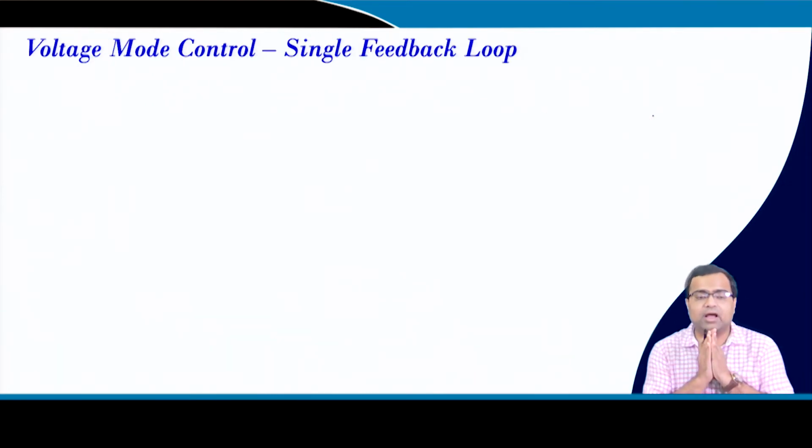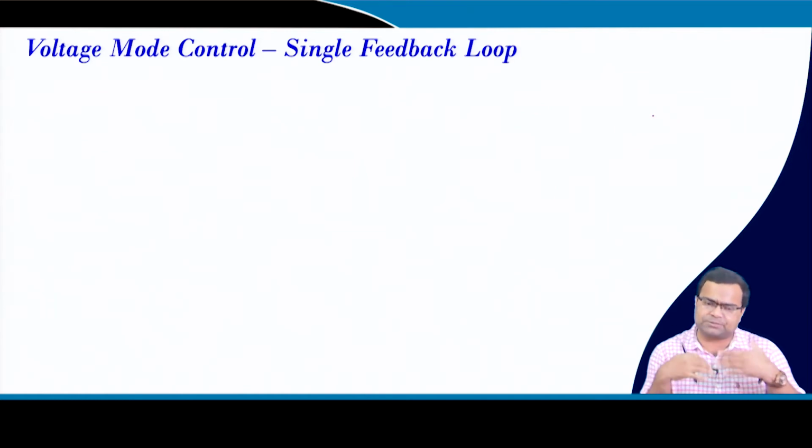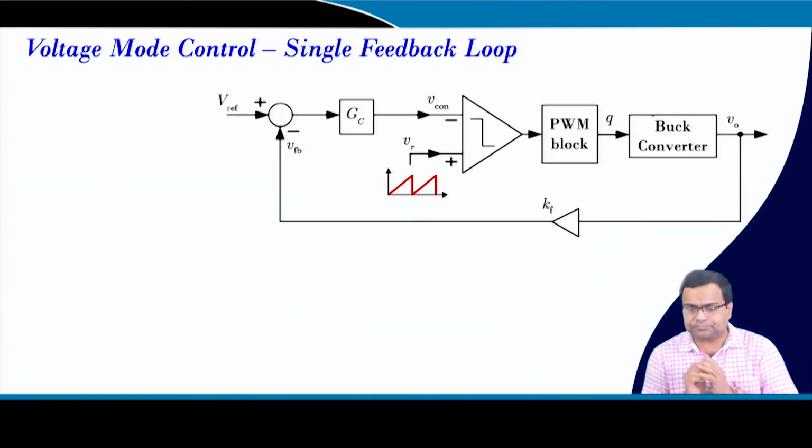Alright. Now, we want to first go for voltage mode control, because in today's discussion we want to talk about single loop control, and in subsequent lectures we will go for two loop control in current mode, but in single loop control we want to restrict our discussion of loop gain analysis to single loop voltage mode control.